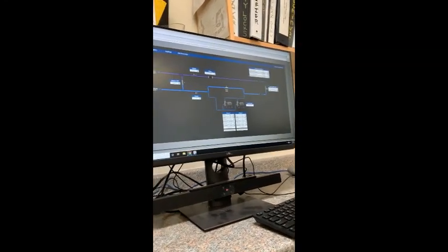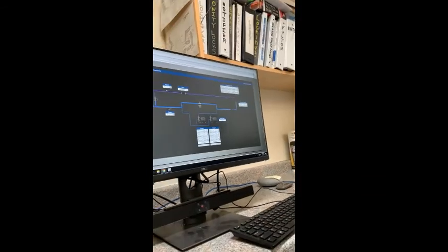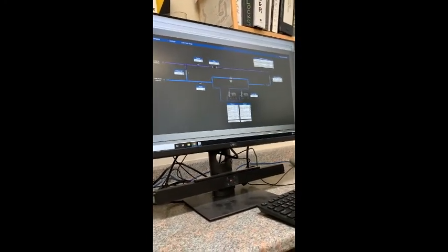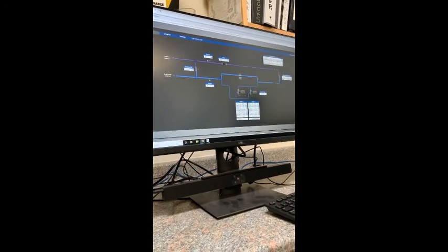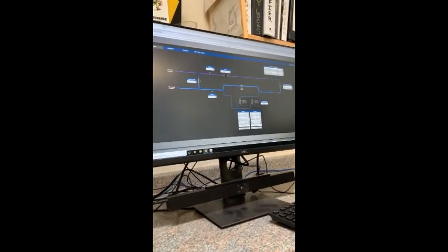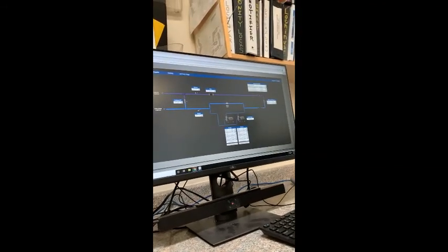And then you can see what the 8th floor differential pressure is as well. If they're feeding us enough differential pressure from up above, and the water's coming down with enough force to supply the building fine, then the pumps won't turn on until the differential pressure drops below a threshold, and then it'll fire one of the pumps at a certain RPM.